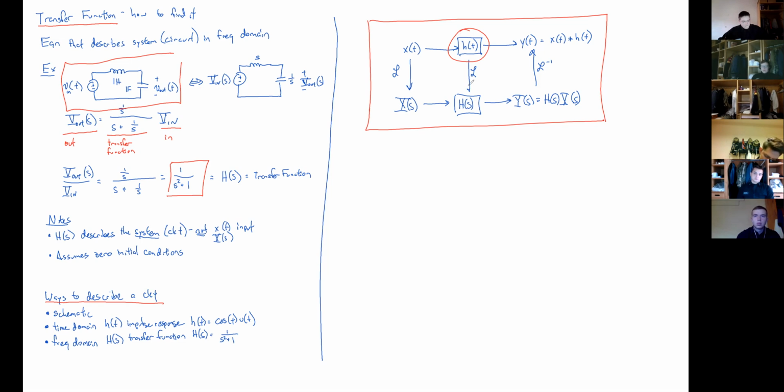And what you didn't know several classes ago was how to derive this, which is what we just covered over to the left. It's to take your circuit, give it an arbitrary V in that you don't specify, find out its arbitrary V out, and then divide the two over here to find your H.